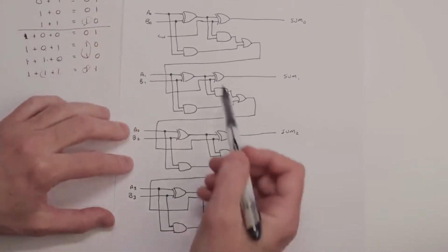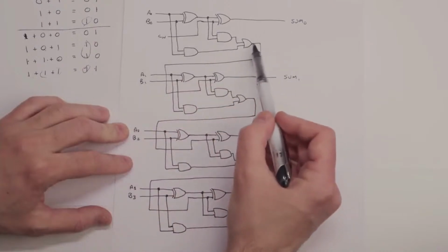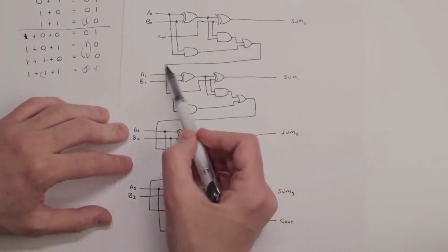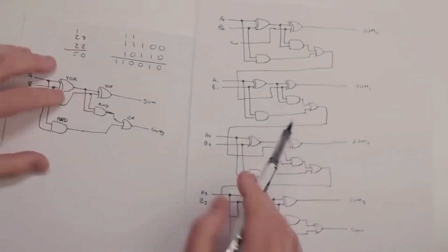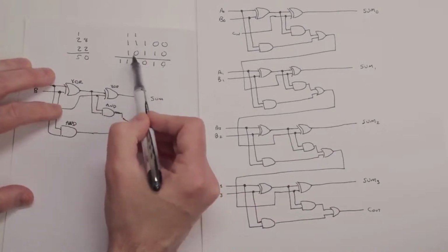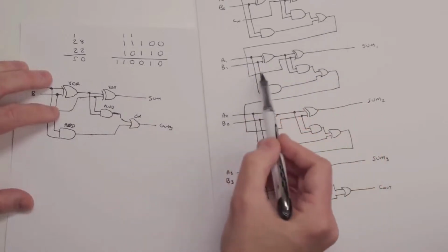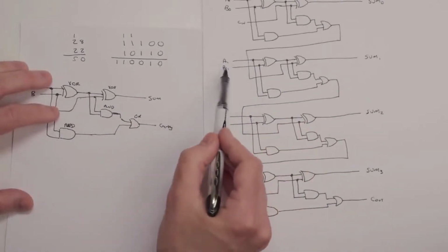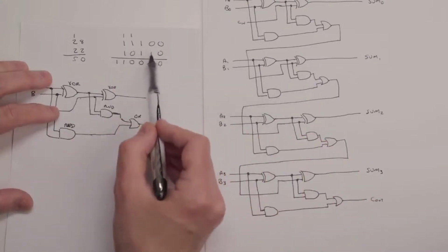For example, I've drawn up this diagram here, which shows that same circuit replicated 4 times. In this case, you have an A and a B coming in here, and the carry coming out goes into the carry of the next circuit. So this is like when you're actually doing the arithmetic, you have a 1 plus a 1, you have a carry, it goes in as an input to the next addition. And so that carry comes into here, along with a new A and a new B, which is going to be the A and B for the second column.